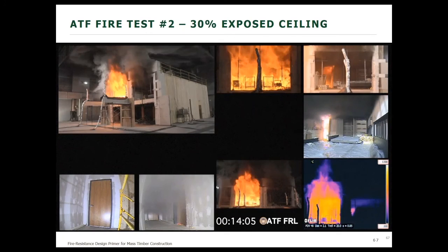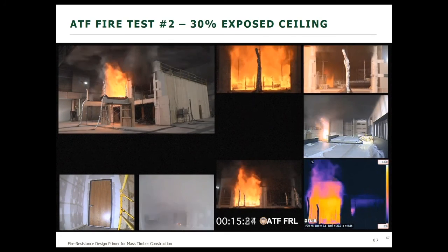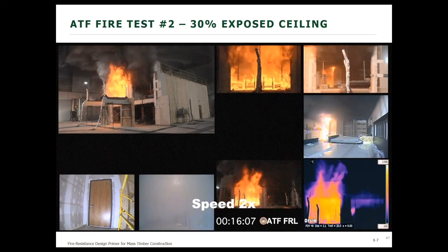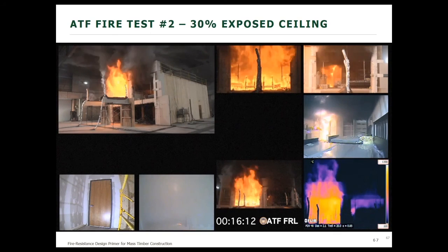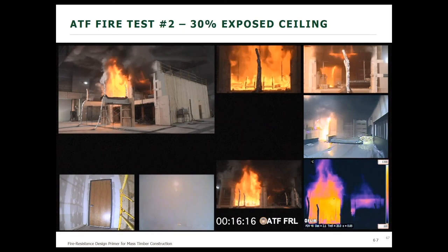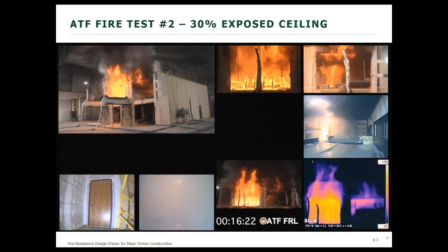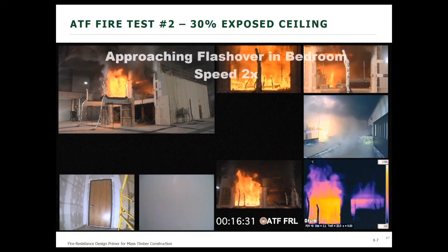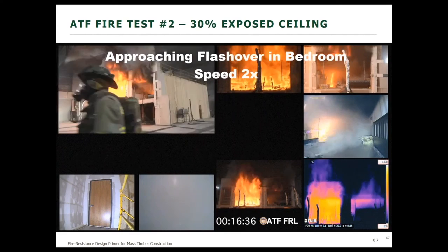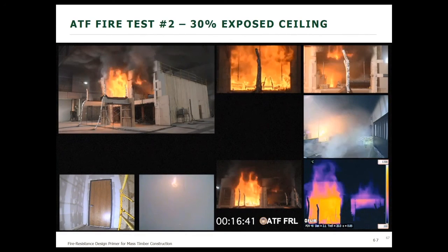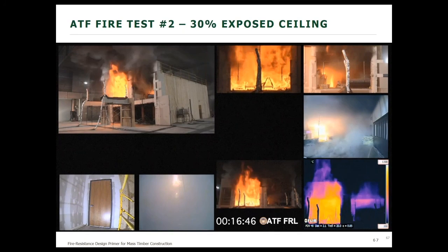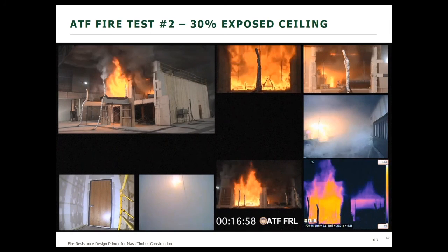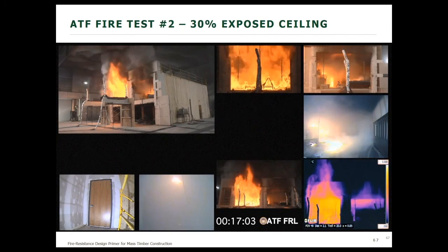It's somewhat of a point of interest, but we were very happy that the flashover, what you'll notice here, was almost exactly to the second the same as the flashover that occurred in both tests 1 and 3 as well. So as you can see, there's the flashover, right at that 17-minute and 20-second mark. Why that was so important is, of course, we were loading all those extra wood cribs in there and trying to make sure that we replicated the same fire load in the same condition from tests 1, 2, 3, 4, and 5.